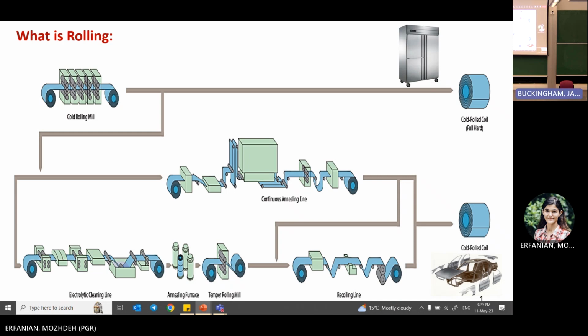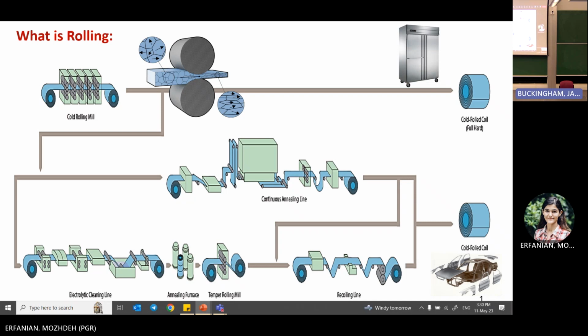I'm not going to talk a lot about the microstructure, but it's still useful to see how rolling affects material properties and also some of the applications. Each tiny unit that you can see here is a single crystal, referred to as a grain in engineering, and you can see that they are randomly oriented. After passing between two rotating rollers, the grains are elongated and all aligned with the direction of rolling. The resulting sheet is very hard to deform, and therefore it's ideal for applications where no formability is needed, such as metallic appliances and structural panels.